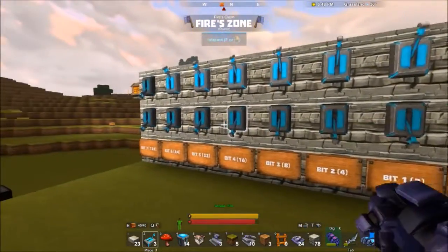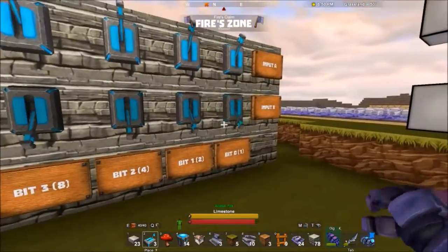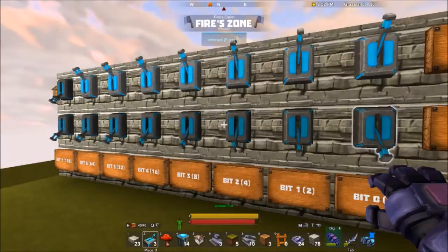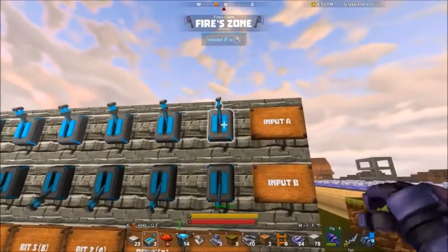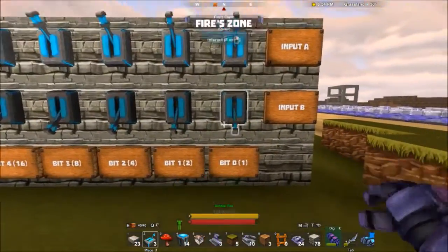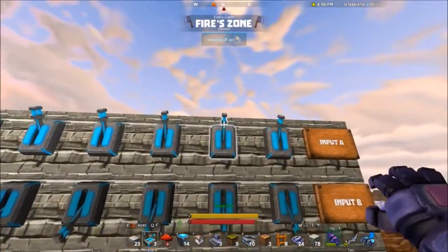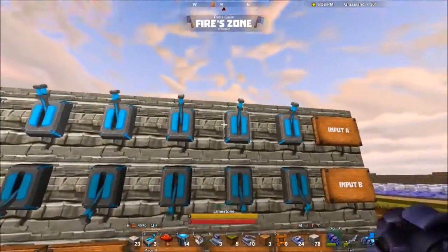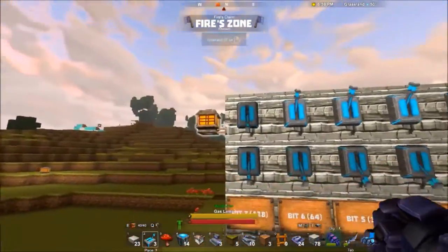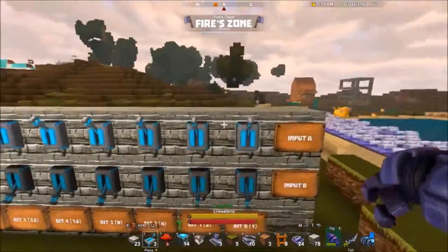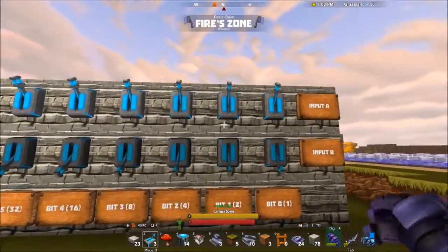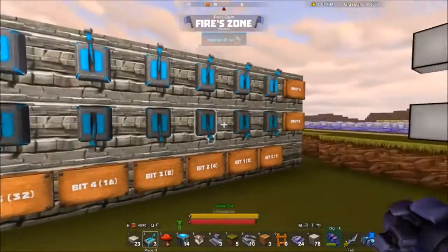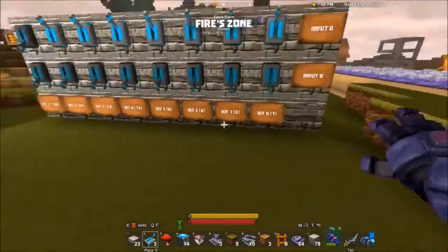You cannot be sure if this one is going to have a carry or not until you calculate this one, and so on. So that's why on the ripple carry adder, which is the normal version of doing it, you will calculate the first one, then you see if you have a carry, you pass it to the second one, you calculate the second one, and that way until you are done with the next one. So this is generally slow on a computer because you have to make many cycles. But let's see here.